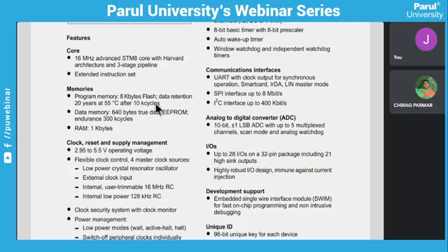It has 8 KB of flash and 10K data retention cycles. You can flash it for 10K cycles. 640 bytes of true data EEPROM. That's the locker of the controller, where the controller stores its valuable values which it doesn't want to forget. And the RAM is 1 KB.